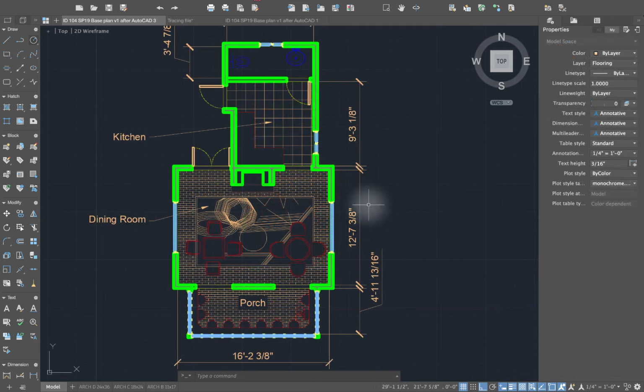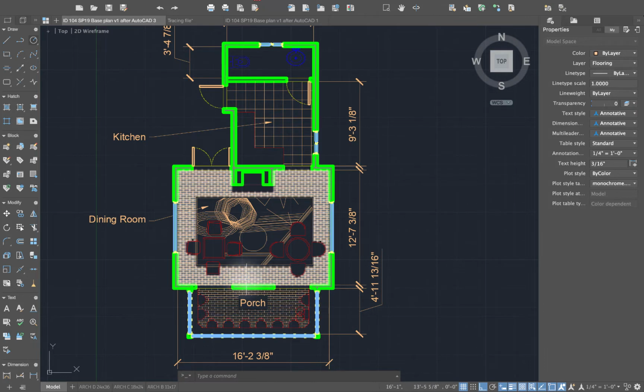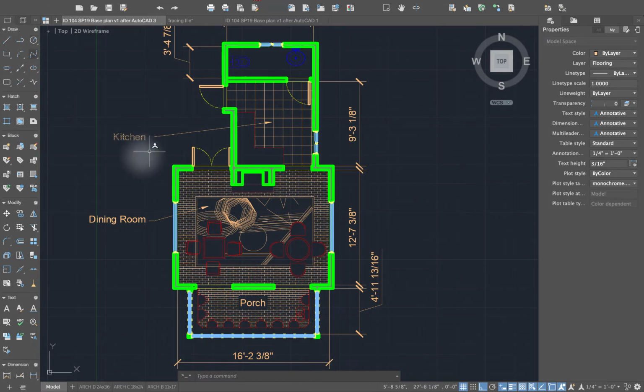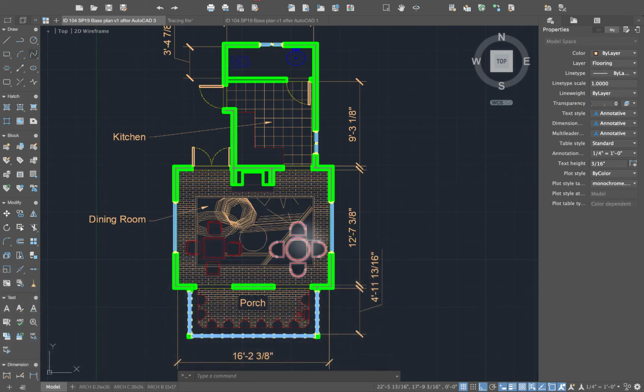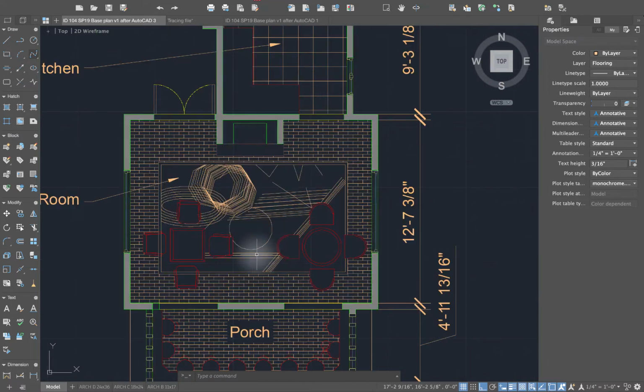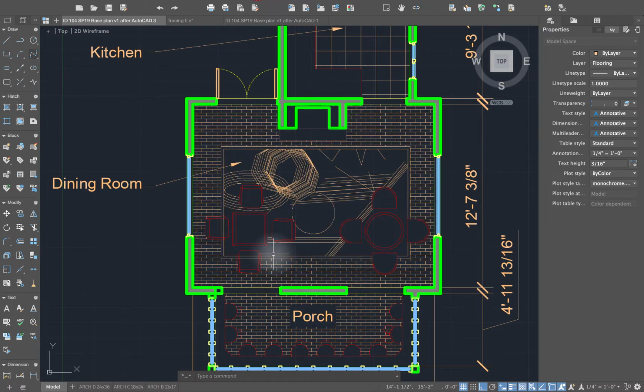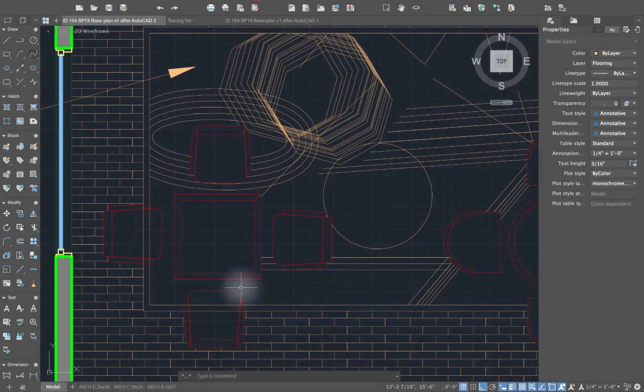Before printing, one last thing you're going to want to do is just give your drawing one last check over to make sure that things are looking the way you want, and also to see if the line weights and the text all make sense. You don't want text overlapping with each other. You don't want arrows going through or obscuring notes or other objects. And also, sometimes what you'll see is that you'll want line weights that don't always follow the layer settings.